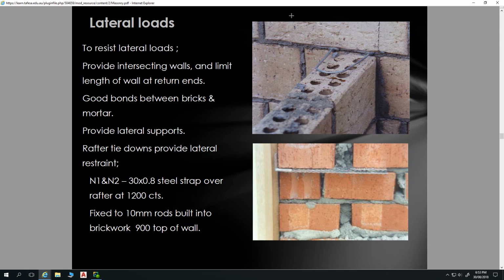What happens when you try to arc weld something that's this thin onto something which is this thick with steel? Well, you have a very difficult time of doing that anyhow to get that joint. So many of them weren't joined very well. But you've burnt all this galvanizing, and it rusts right at this point. And so all of the ties had just rusted or not joined on properly to those I-beams, making the portal frames, and it just took a little bit of wind on the side of it, and the whole thing came down, fell outside, and fell on some adjoining buildings, which wasn't a very happy scenario for the neighbours.